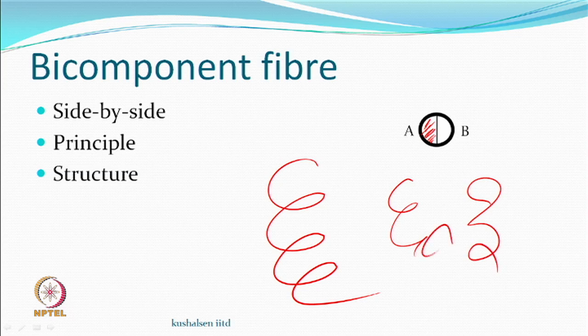So, you may say, well, this is a helical structure, this will be a stretch yarn, why are we actually working on it under the bulk yarn category? So, it so happened that people were not able to get the kind of helix, and the number of helices per unit length was not so high for it to be considered so nice that it is going to replace a stretch yarn, right. But they would cut it into staple and then use it, and they say, oh, this looks like a crimp. So, one fiber, the other fiber, and so on and so forth. So, they made the yarn.